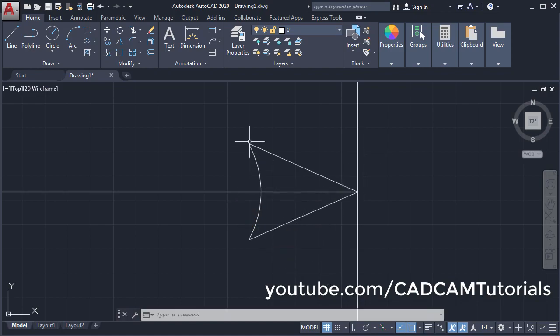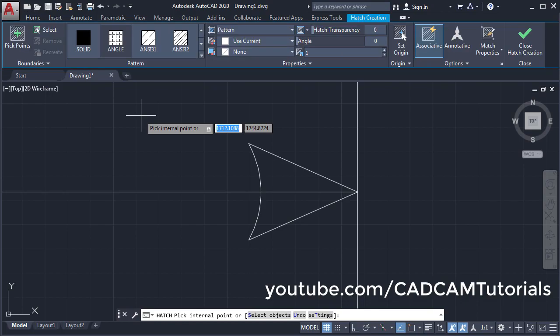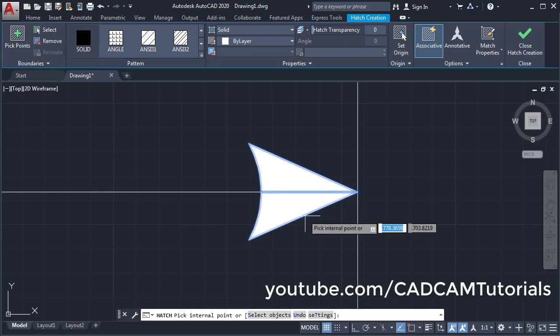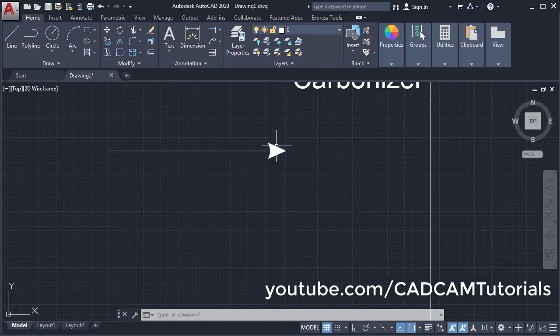Then to fill this arrow we will use hatch command. Click on hatch, then click on solid, then click inside this arrow, then click on close hatch creation, zoom minus.